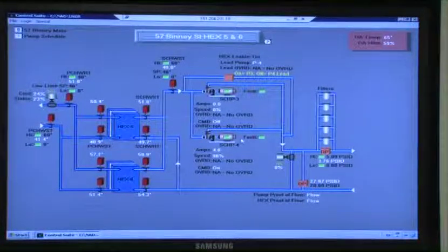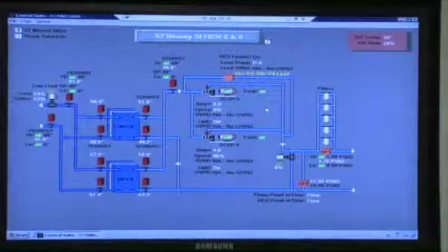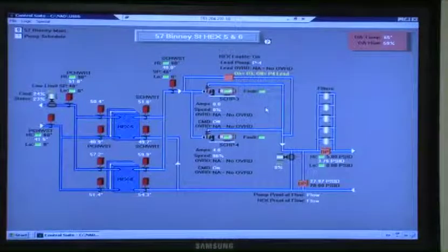Or if you get into a situation where you have to, you could go into bypass mode, put it at 100% across the line, and that differential pressure valve is going to go wide, because you get so much DP, it's going to open. The third thing is if you have a complete failure of this, there is a chill water bypass valve. I don't see it up here.